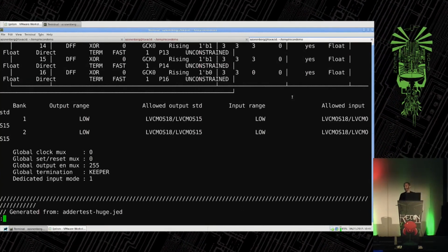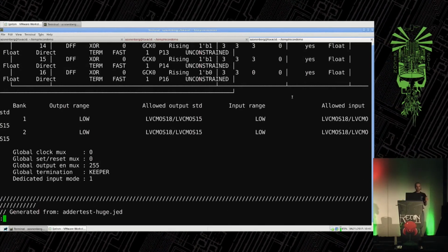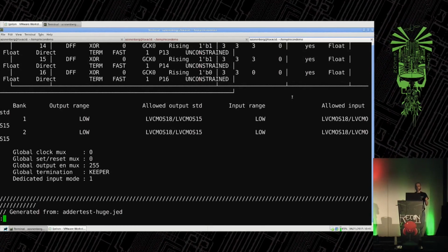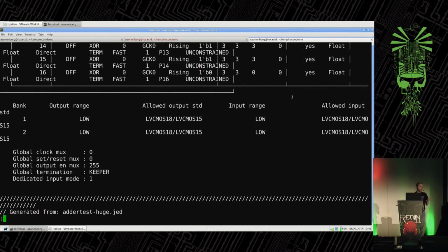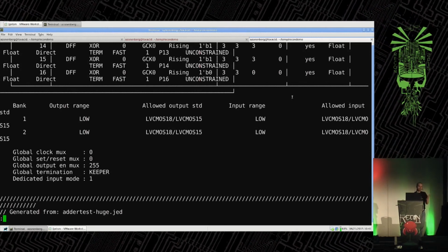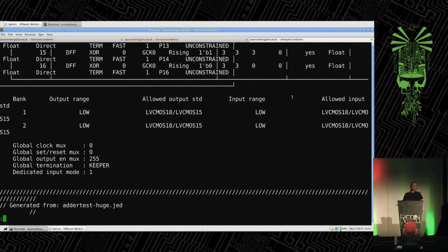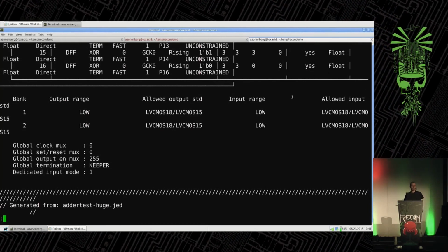So my guess is what this does internally, and I have not fully reverse engineered all of the I/O driver circuitry, but what I'm pretty sure it does is select a single threshold or another, and then thicker or thinner gate oxide in the output. There's about 4 or 5 different sets of drivers in the output for fast and slow, different voltages, and so on. I haven't actually done TEM cross-sections and measured the transistors or anything like that. It wasn't necessary for this.